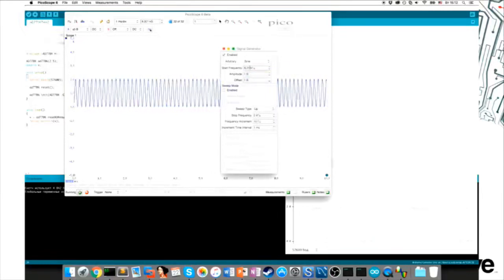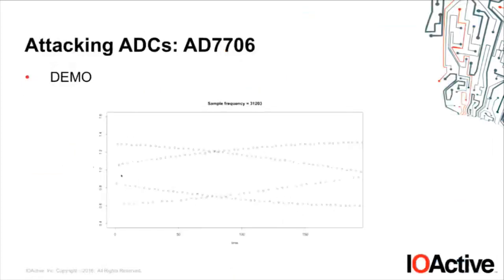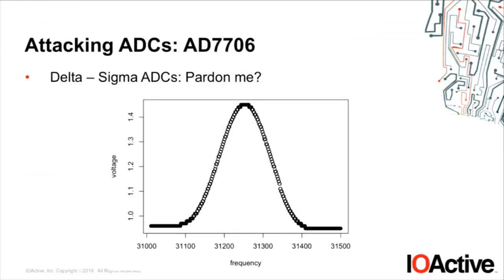So this is a very important thing, right? We are generating a signal that would cause a problem to an actuator, but the system PLC would think that it's reading something completely different. So using the frequency, we managed to make the safety-critical system think that things are okay or not okay. If the monitoring system is expecting this type of signal or any other value that we can generate through here, it will read it and say it's totally fine, but we were injecting something completely different. This is what happens here. It's more or less the whole sweep between the frequencies around that specific point.